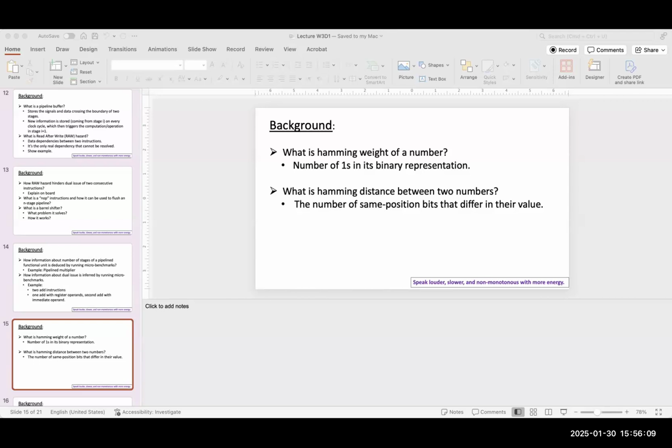Then definitely they are putting in a multiplexer, because the result which is sent to the next stage depends upon which kind of instruction you are executing, right? If you are executing, let's say, a load store instruction, the result needs to go from this input. And if you are doing an ALU instruction, the result needs to go from this input.